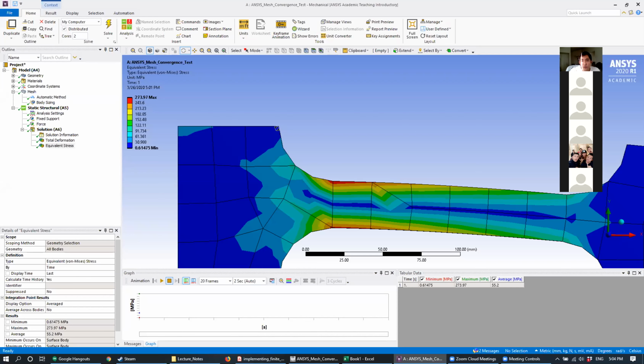Yeah, the bigger the fillet that you put there, the more it would help. Of course, you don't want to put too big a fillet because it might be unfaithful to your original geometry, but any little bit will help. Because when you have that 90-degree turn in a finite element simulation, the stress can really concentrate there. So if you do have a sharp corner in your geometry, you can put a tiny fillet, like you said.